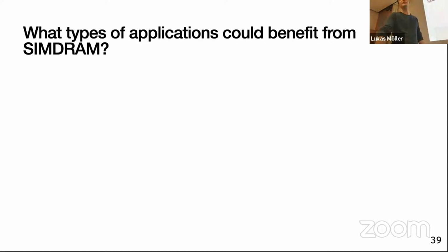Wait, can you do anything conditionally in SIMDRAM? You have branch-not-equal-zero instructions, and you have micro registers which store values in the SIMDRAM control unit, but you can't combine both of them. You can have registers in your SIMDRAM control unit and do stuff based on that, but you can't load memory into your SIMDRAM control unit.